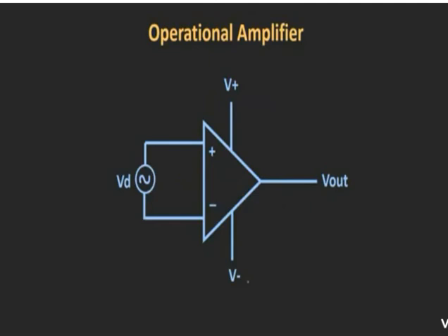So whenever this operational amplifier is used in an open loop configuration, even if we apply a small input signal, you will find that the output will get saturated towards the positive or the negative biasing voltages. So this characteristic of an operational amplifier is practically useful as a comparator. So this is one of the applications of this operational amplifier.